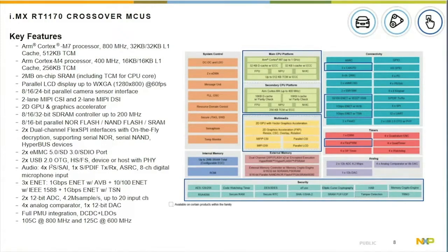This device has all the same attributes, functionality and features that are part of the i.MX RT1150 design, where we have great demos showcasing that you can run full BLDC or PMSM FOC control motors simultaneously. This part has the performance and the peripherals, such as that Flex Precision PWM control, to handle those requirements running in parallel. And then the last block to point out is that hefty security module that allows on-the-fly encryption, decryption, and secure boot.